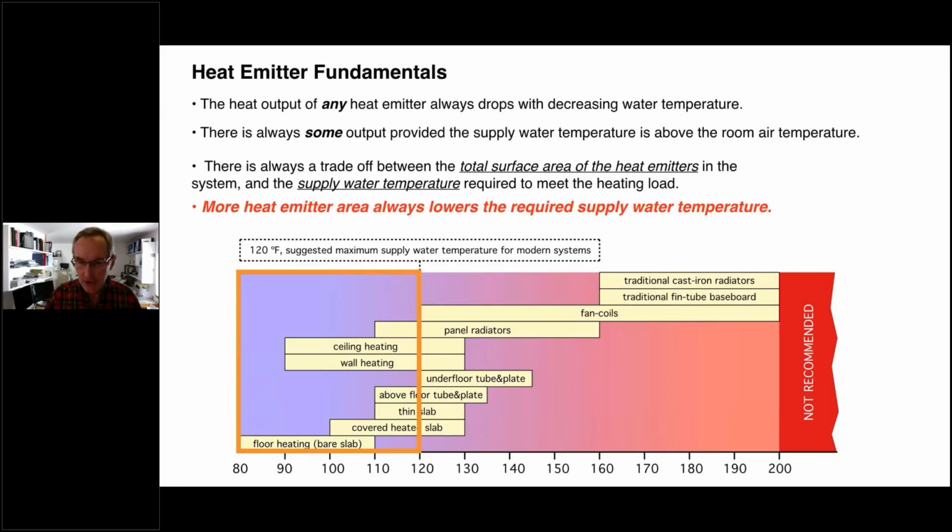Again, that is not an ASHRAE standard. To my knowledge, it's not in a code, but it's a good target. It certainly brings your distribution system within the range of not only heat pumps, but good performance on modulated condensing boilers, good performance from thermal storage systems as the water temperature in the storage system goes down.